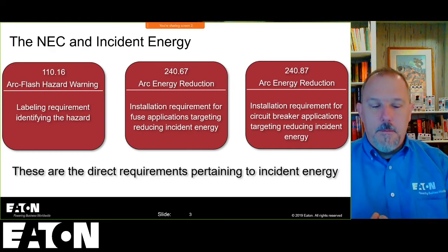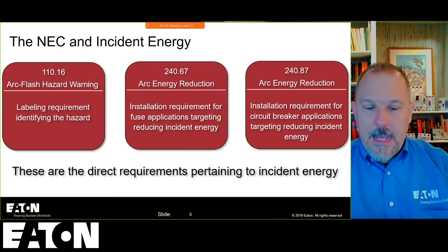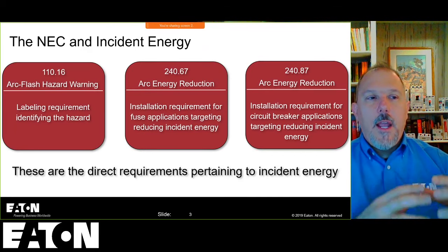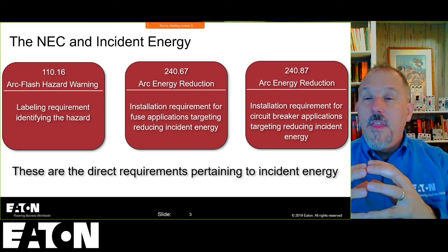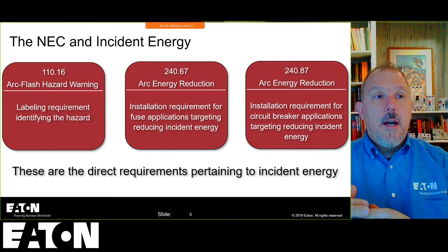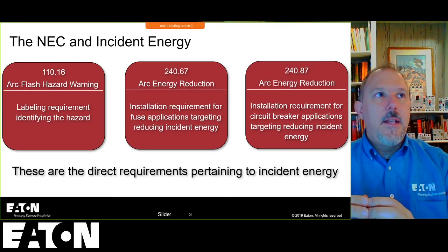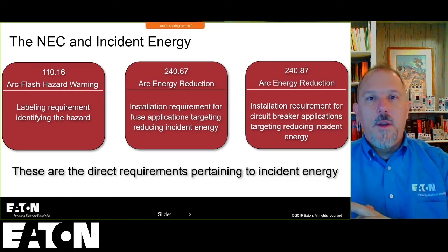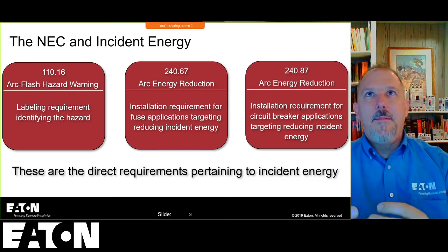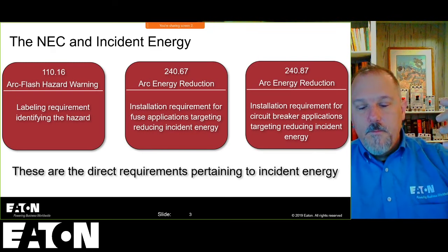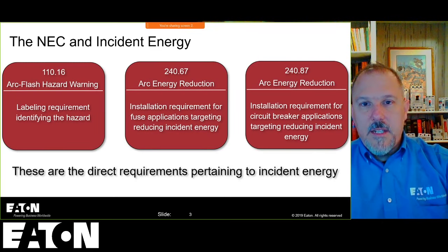So here's what happened. Back in the day, they went from ungrounded to grounded. When they grounded the system, the fault currents went up. They had higher fault currents. I say that, and we could have a debate on that, but one of my discussion points is that your first fault in an ungrounded system is free, right?